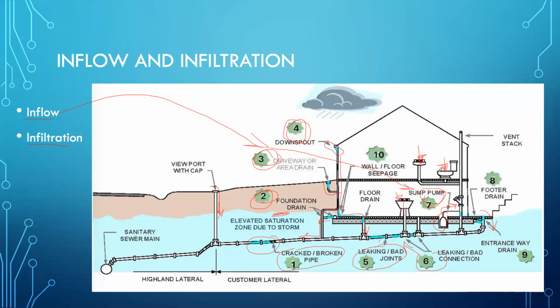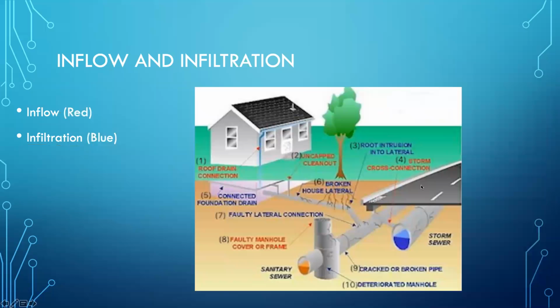So this connection, and that connection are indeed authorized. Those are intended sewer connections. And so what we can see in the drawing, at least in this drawing, is that there's 3 intended connections and a whole bunch of unintended ones. And collectively, the unintended ones combine to add additional volume to the system called inflow and infiltration. Here's another cartoon depicting the same kind of scheme. In this one, it's nicely color coded.